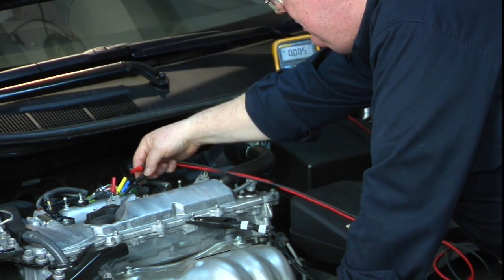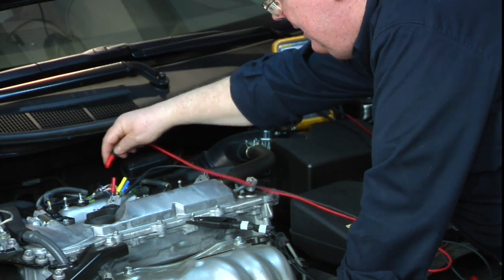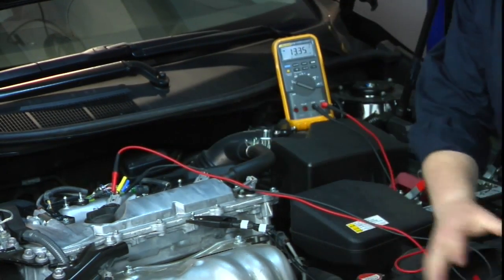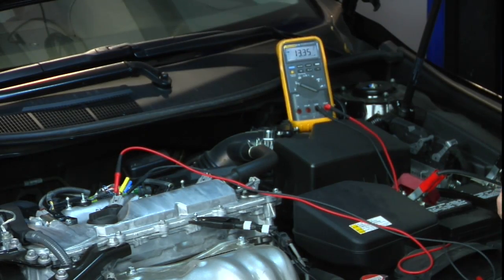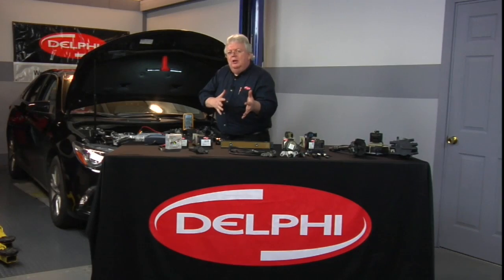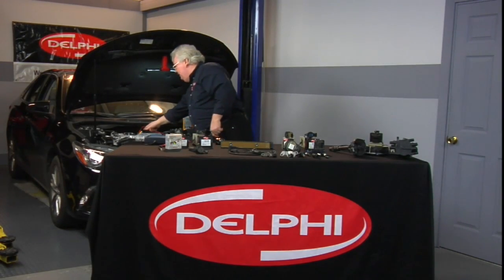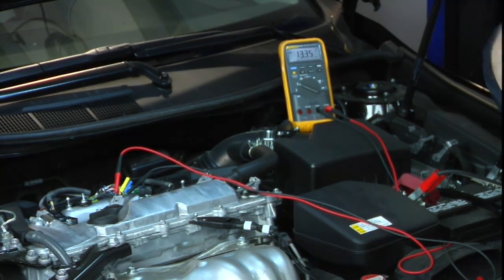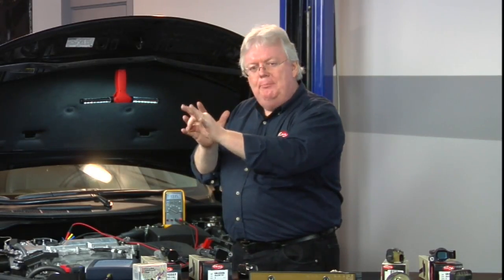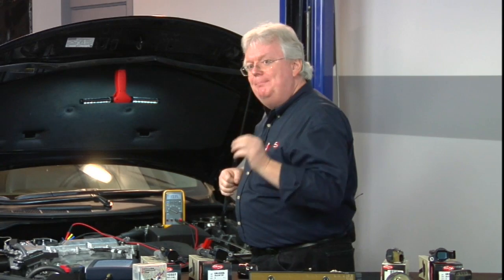So we'll back probe in here directly with our meter. This is showing you guys that just use the meter, some things you can do. And we've got 13.3 volts. There's no need really at this point to go a little deeper. We could, if we wanted to, back the pins out or actually disconnect the connector, get some mating male pins and put a substitute load in there like a light bulb or something and do a voltage drop that way, but I don't think we really need to do that at this point yet.